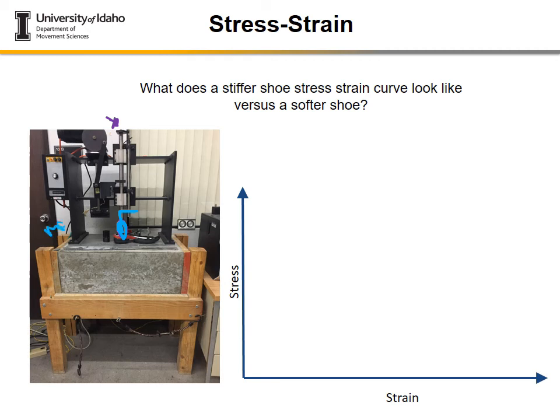So mgh will be the potential energy, and then when it hits, we'll have 1/2 mv squared, which is going to be the kinetic energy. And by calculating the deformation of the shoe based on how much it falls, we can calculate how much energy is stored. And so what happens is, because of the height and the depth of this, the stress is calculated.